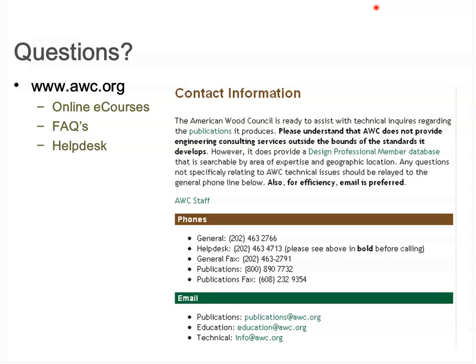Okay, here's a response to the question about inelastic deflection. The comment here is, I believe that is the amplification factor, C sub D in ASCE 7, section 12.8.6, which is then used for story drift and seismic gaps. So thanks for that bit of information there about the inelastic deflection. That looks like it's covered in ASCE 7, section 12.8.6.